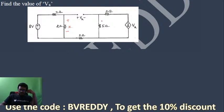So if I call this current, how much is this current? This current is also Vx. Now we get this voltage as 5Vx. Here there is no flow of current, current is equal to 0, so this voltage is 0 already.